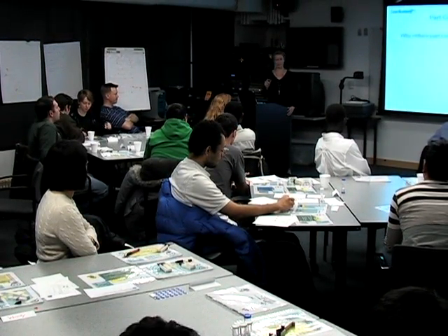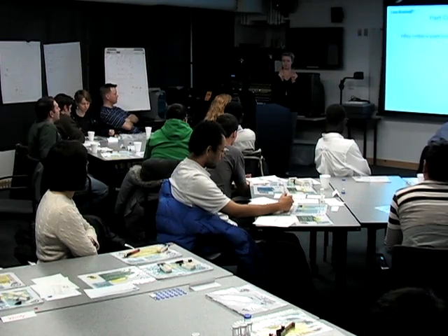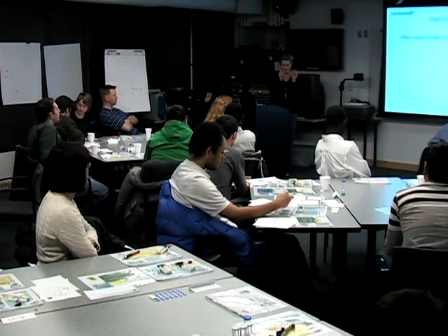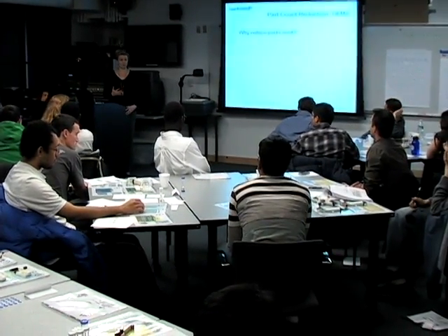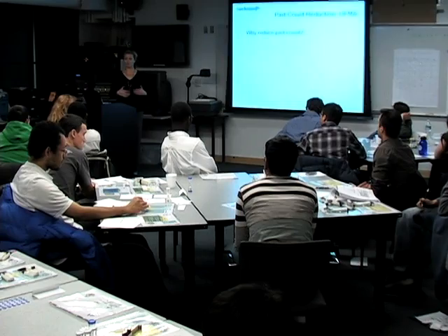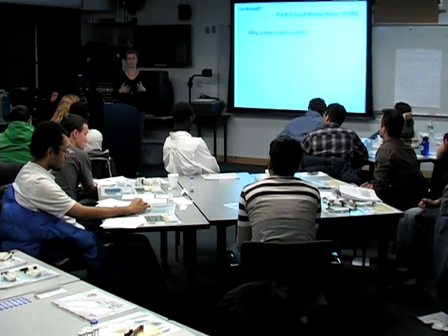If you're reducing the part count, each part has a specific tolerance to it. The more parts you label together, the bigger that uncertainty and potential tolerance grows. You have fewer parts, that comes down. What else? That is good. Fewer chances to make mistakes, yep. Because every part I handle has some probability that I'm going to make a mistake with it, and I have a few of those. Yep.